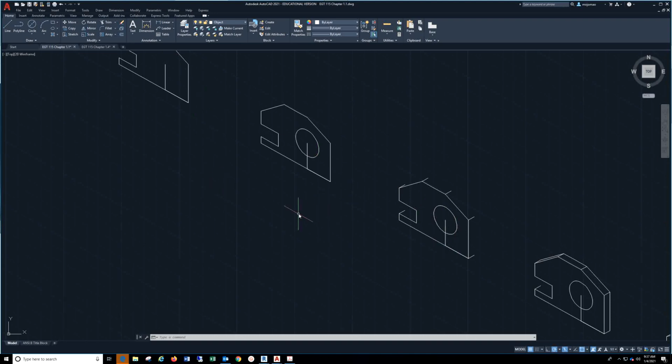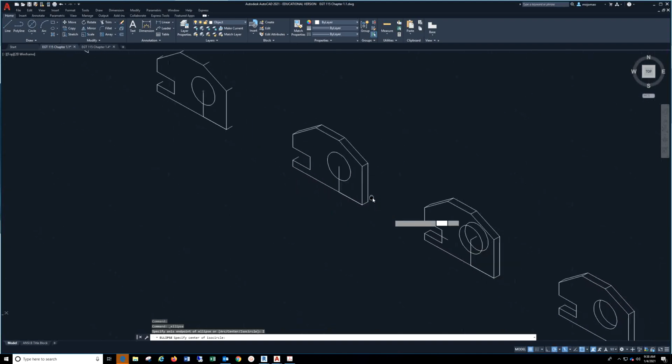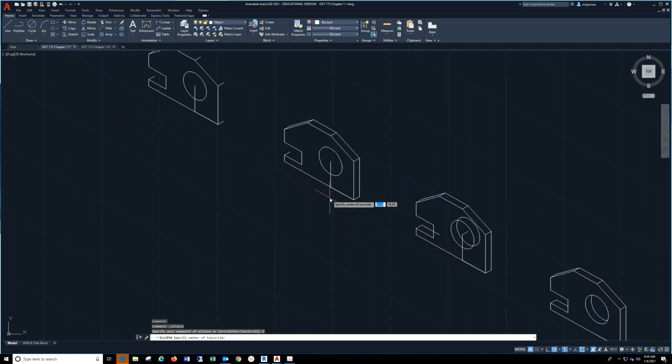And then for the circle, you're going to go ellipse, iso circle, and type in the diameter, which is 1. Pick this point, type in the 1, and you'll have the circle. Okay? Come here, and all you have to do is pick one of these lines, offset it 1/4 inch, and hit F5 to switch your line direction. And once you have one of these drawn at 1/4 inch, you can just copy those around, because there's 1, 2, 3, 4, 5 of those.